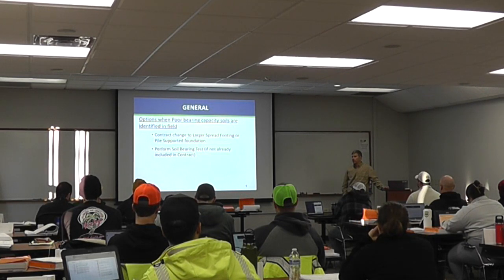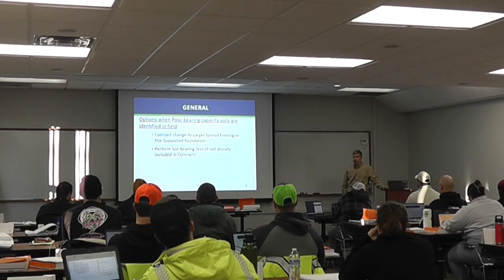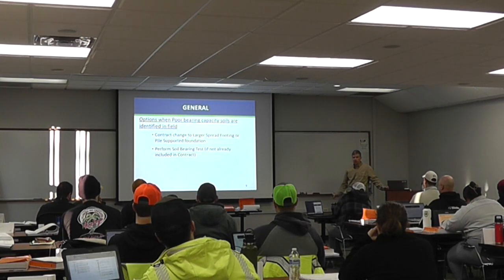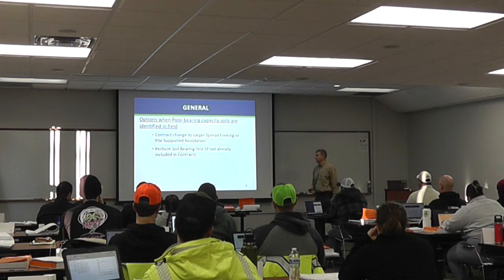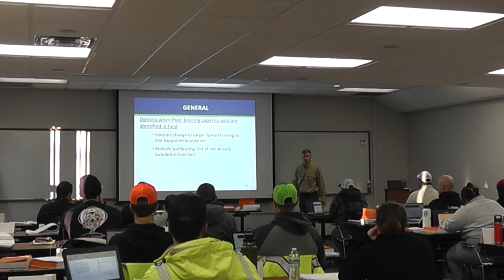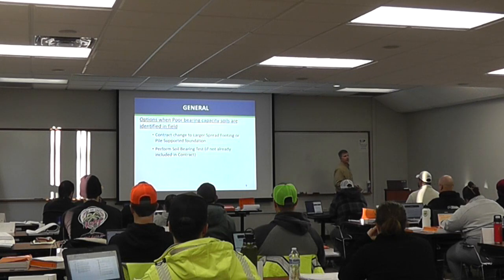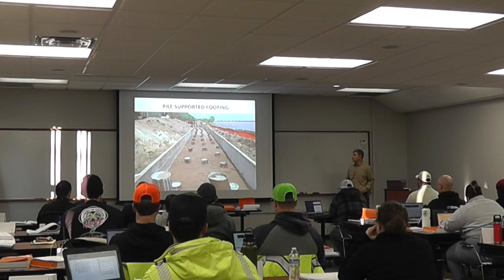I went out there and yeah, it looked a little soupy, but we did a little bit of dewatering and it seemed like it was going to be just fine. And it did. We built the spread footings. The bridge has been in service. I never did notice any settlement issues on that bridge. So ultimately it did work out. Make that call to the regional guys and they can help determine if that is indeed right.